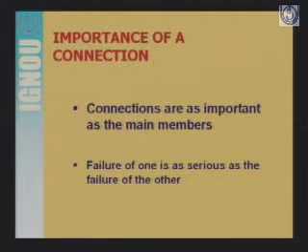Now, what is the importance of a connection? You should keep in mind that connections are as important as the main member, because if one fails, then the basic purpose of the structure fails.